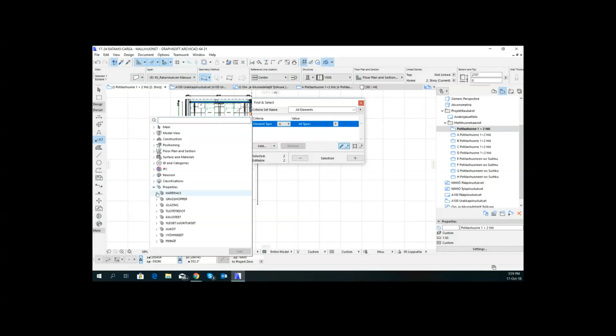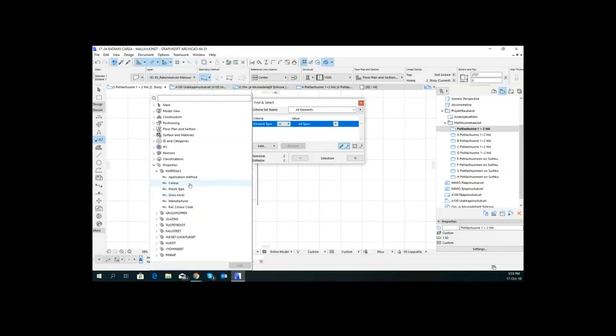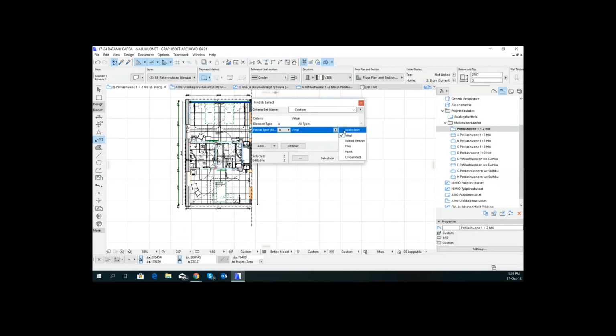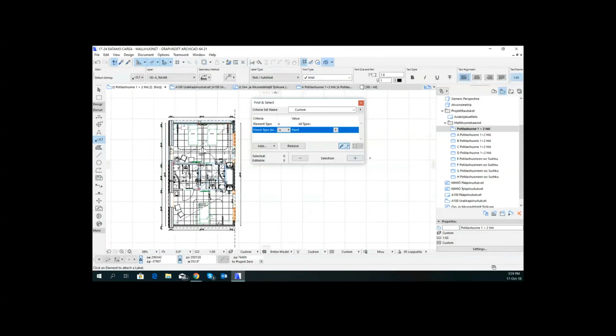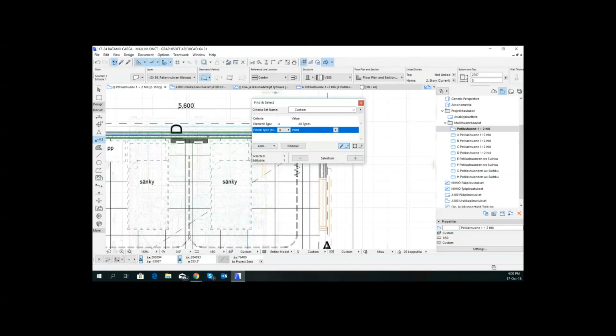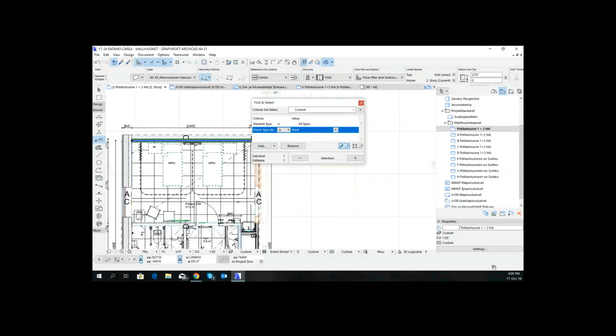properties as well. So then we can search for, say, all walls with, let's say, paint. And it's found me 2 walls. So I've got 1 wall with paint. So you can then find things by these little classifications. And also it's all stuff that can be manipulated, like we were talking about last week in the schedules and manipulating data in Excel.